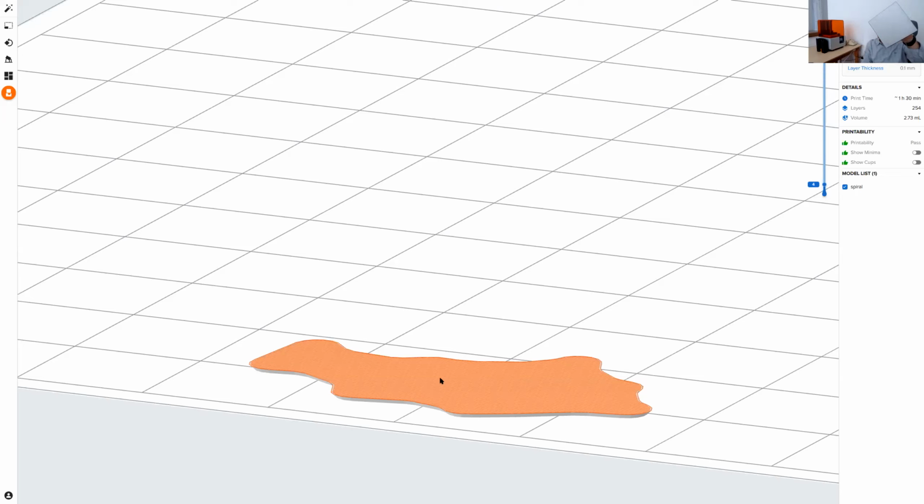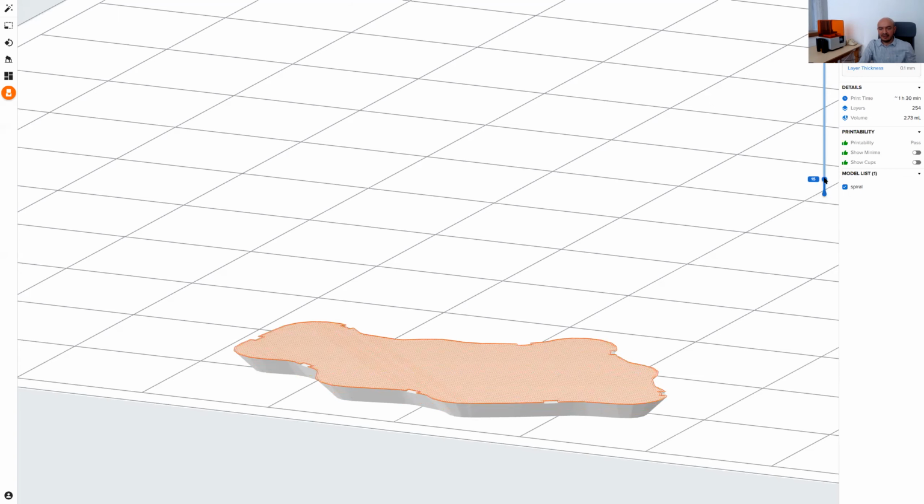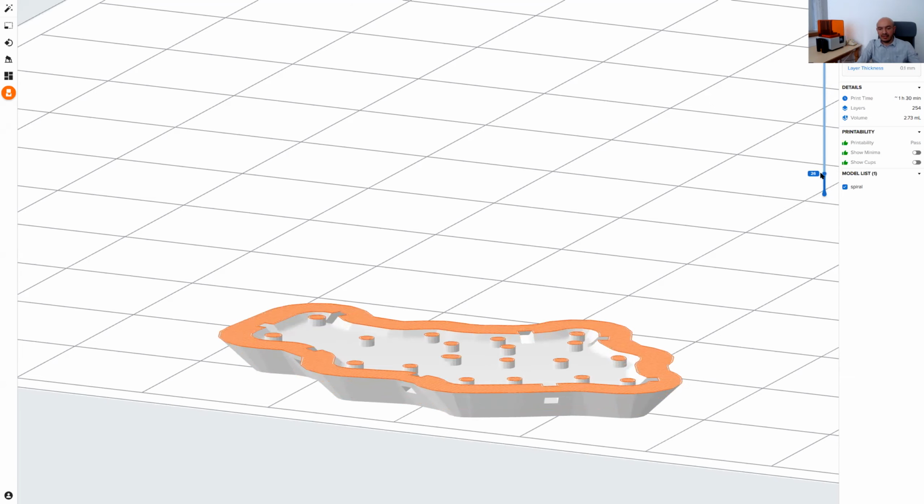If you print your part right on the build plate, it will be quite sticky and you will not be able to remove it from the plate. That's why we prefer to have such a raft underneath. It has some angles here, and it becomes easier to remove with a knife, and things become much simpler. Now you see that the support structures have started to be built.